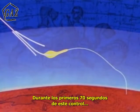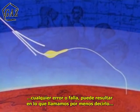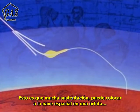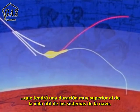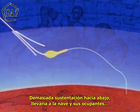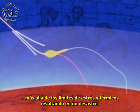During the first 70 seconds of this control period, any error or failure to correct an error could result in what is called, in great understatement, a non-recoverable situation. That is, too much lift-up could put the spacecraft and crew into an orbit that would last beyond the lifetime of the command module systems. Too much lift down could take the spacecraft and crew beyond the stress and heating rate limits and result in destruction of the command module.